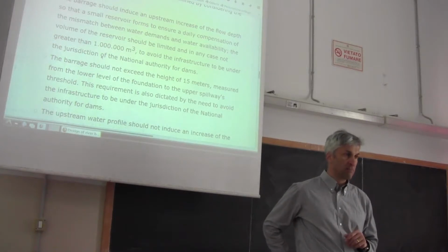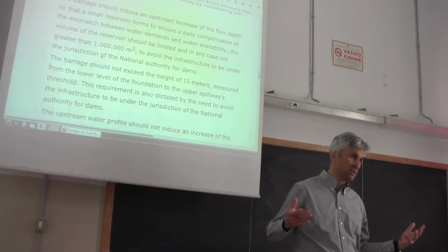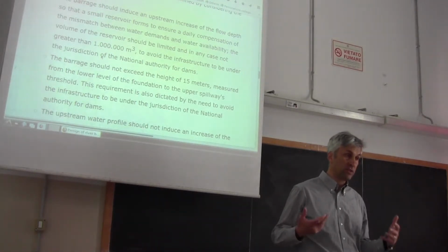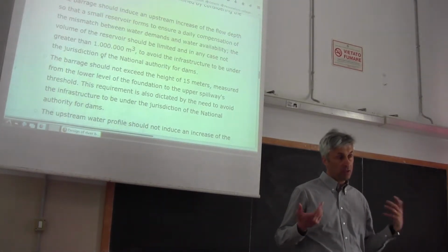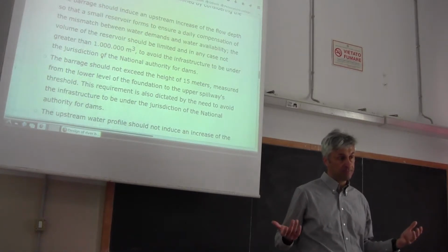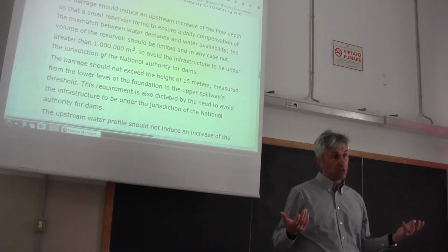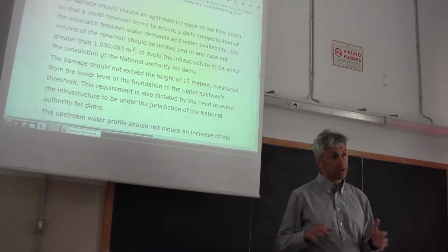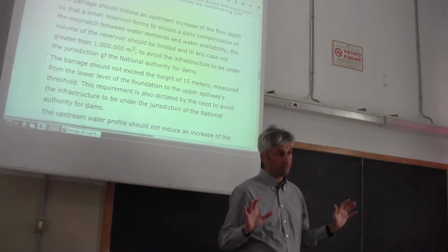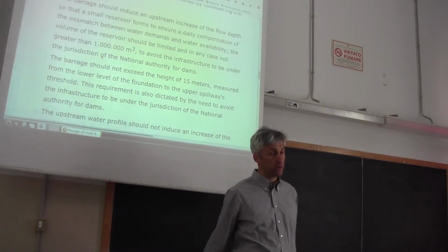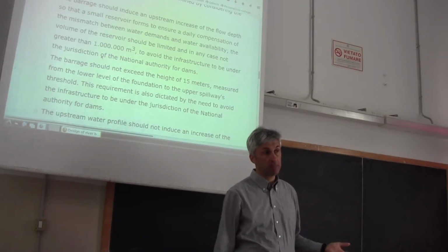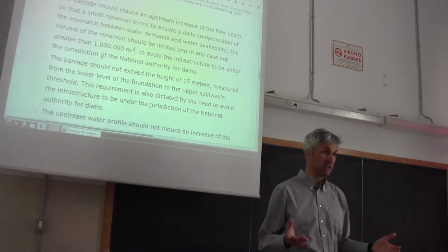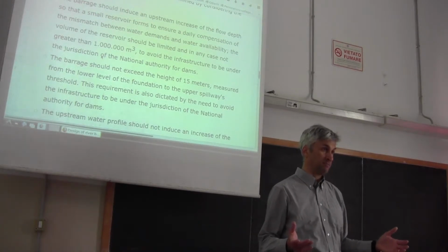Which means that in some periods of the year, you may not be allowed to divert any water, because if you don't have from the river a flow that is at least the required environmental flow, you can't take any water. And this happens usually when we build, for instance, run-of-the-river hydropower plants. We have periods in the year where we can't run the plant.